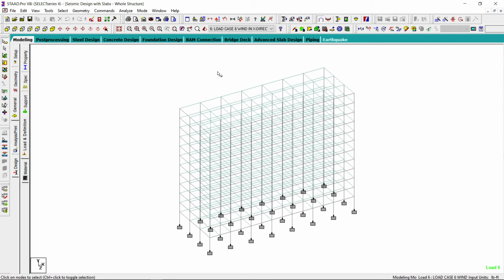So here I conclude. Design of the structure is not a big issue, because this building falls in seismic category A. And in seismic category A, there are no special requirements. Maybe I will design this building for other seismic categories like B, C and D, and we will see what the implications are.